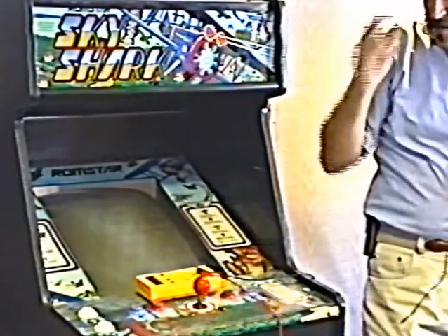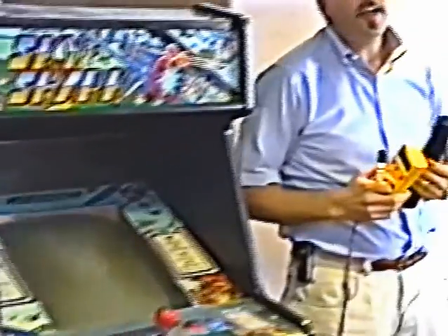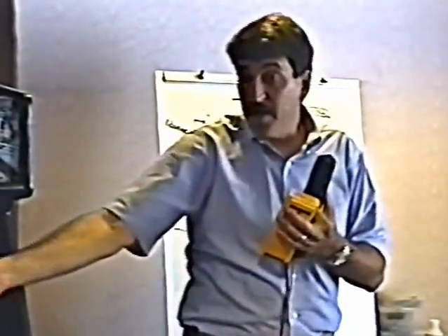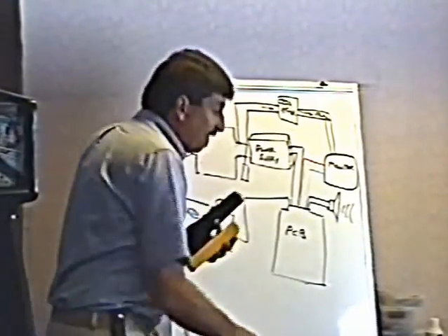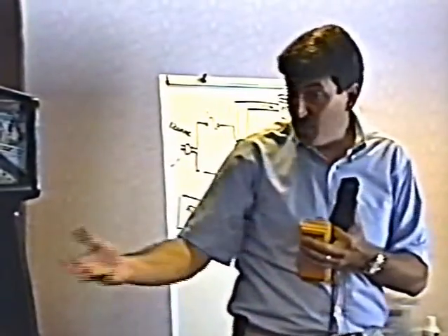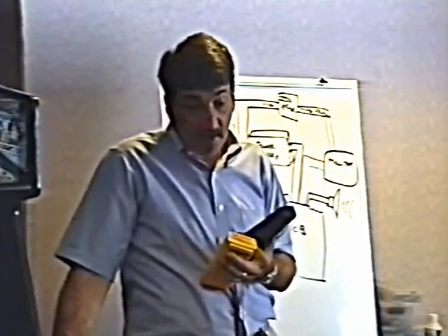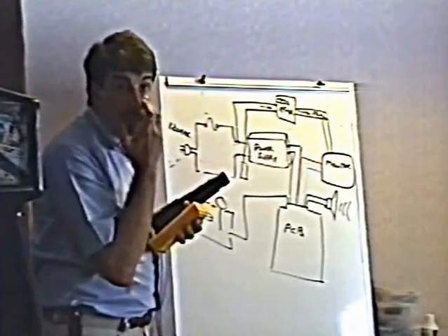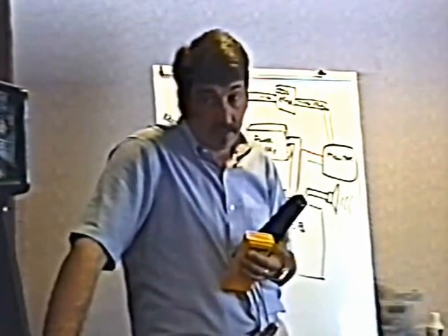On the other hand, if I coin up the game and I do not hear any game sounds, I don't worry about the fact that I'm not seeing anything on the screen. I don't start working on the monitor. If I coin it up and I don't hear any game sounds whatsoever, the monitor isn't bad. You probably have a power supply failure. Your power supply is probably not putting out the 5 volts, and of course I'll tell you how to check that in just a second.